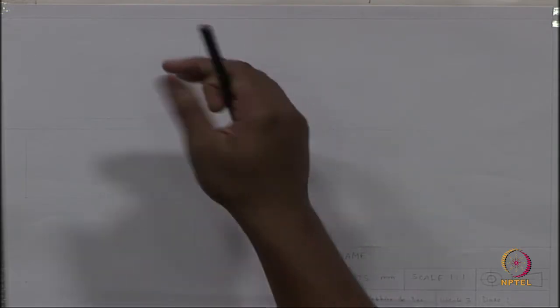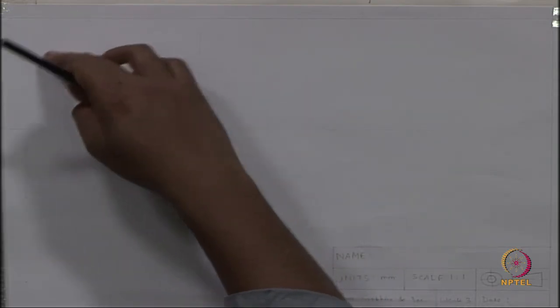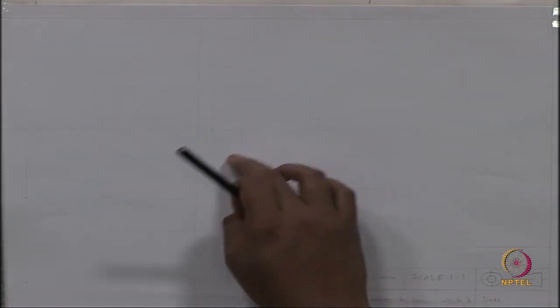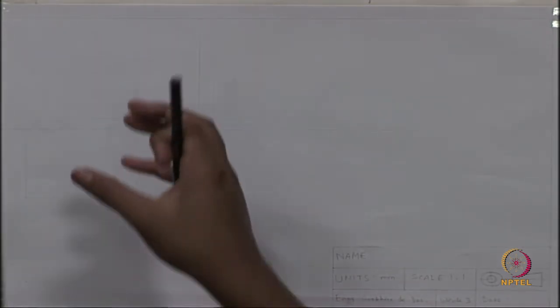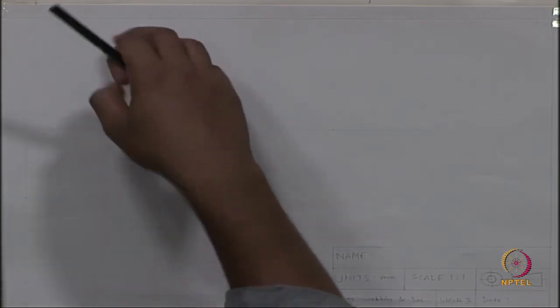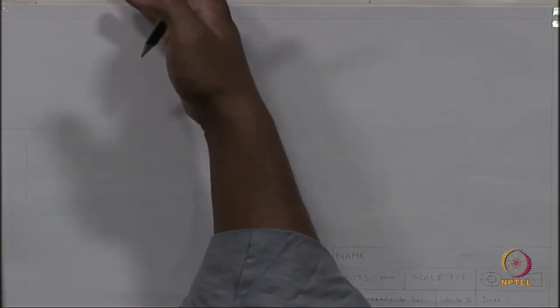and from the space we can understand the top view will come here and the side view we can manage here. So, your first work is done, dimension wise you are safe. If you start making the front view here, it will go out of the sheet, your top view will go out of the sheet, that is not desirable at all. Initially you have to understand it.